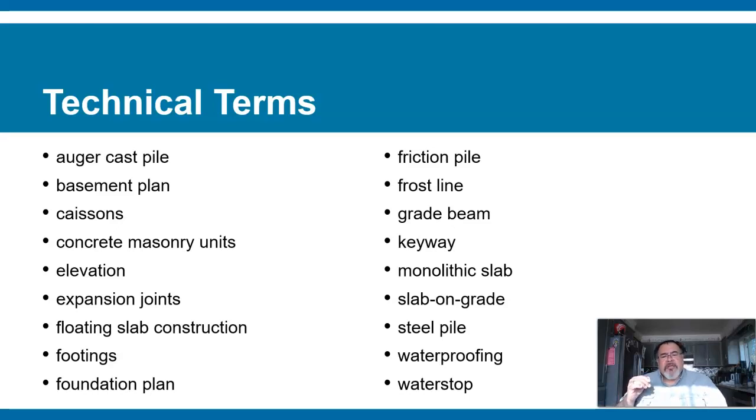And that particular one lineal foot would represent so much amount of a cubic footage or a cubic yard. So it could be a percentage of a cubic yard, for example. Then all you will do at that point is measure your lineal footage and multiply by that unit that you've used to determine what one lineal foot would represent.